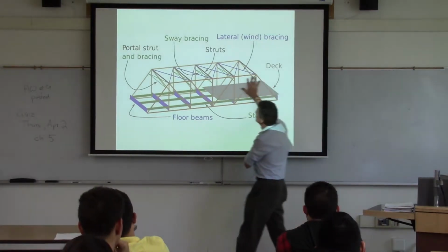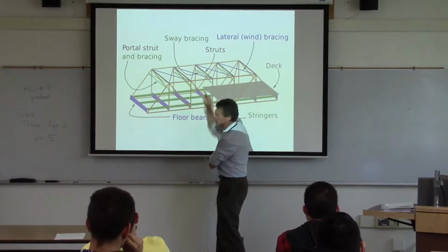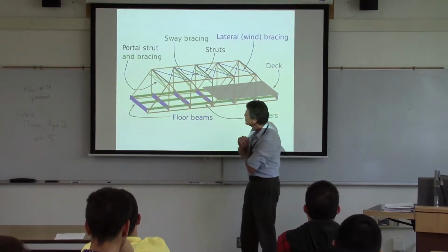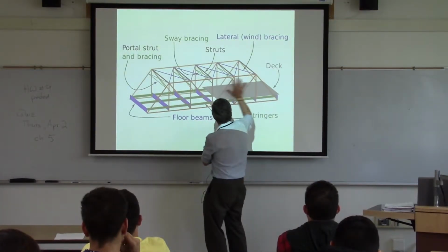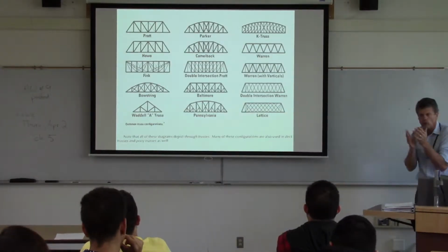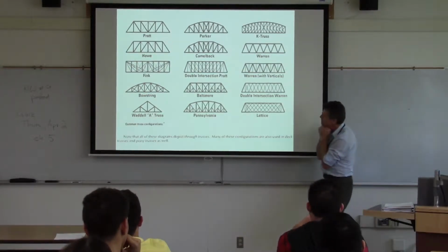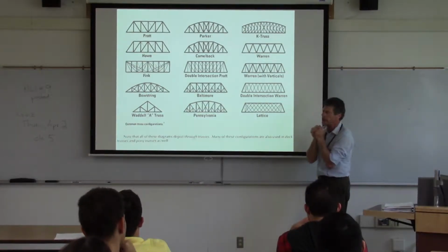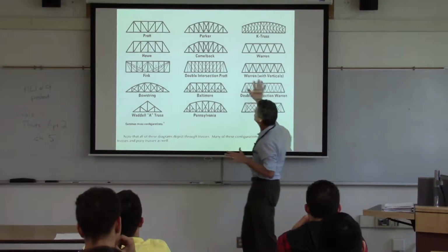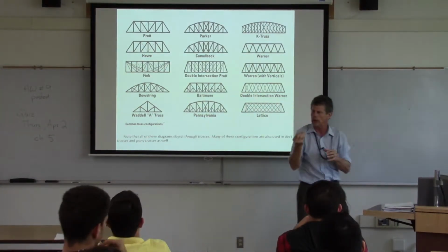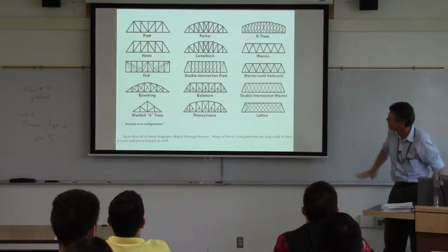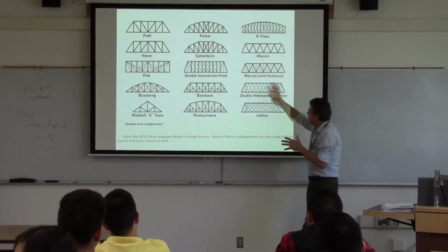But where I'm going with this though is that when we look, there's bracing going across there that's going to be doing stuff for maintaining it against wind, possibly something from the stream hitting it or something like that. But the main load carrying thing here, you'll notice, is all in a plane. And what we're going to be doing in the next couple of lectures is looking at these trusses. And what we're going to find is even though they're three-dimensional, we can analyze them in a two-dimensional sense, because the main load-carrying portion, again, is going to be this orange area there.